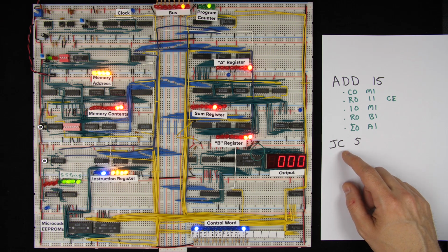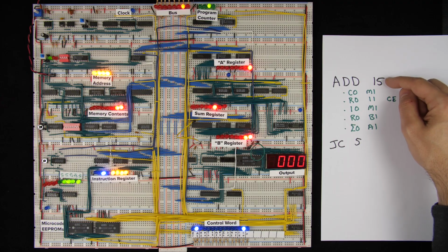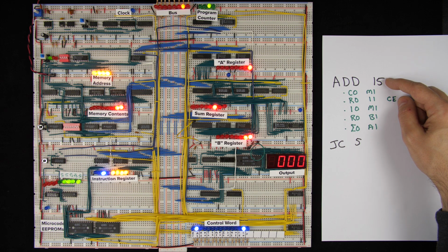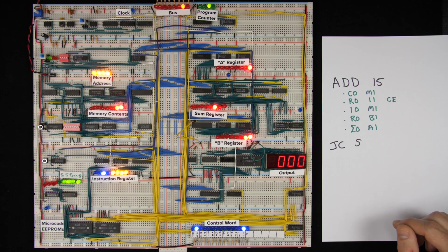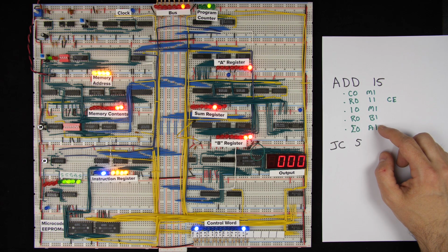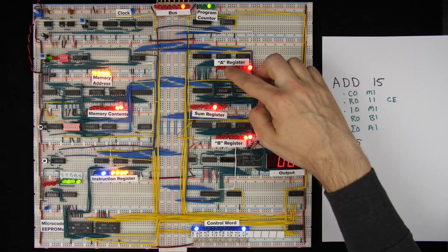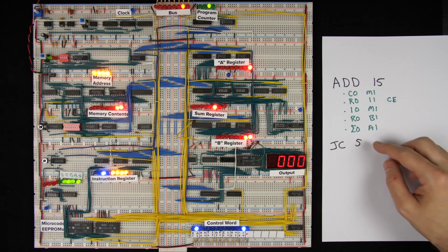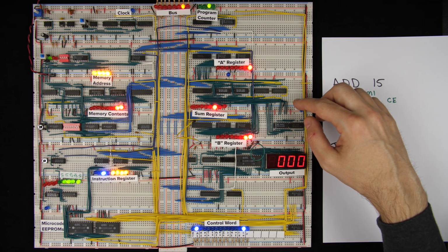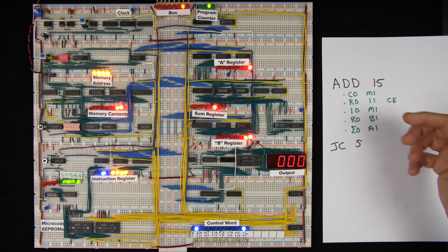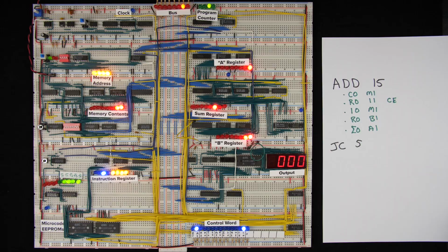How do we keep track of whether this add or subtract instruction that we're doing here resulted in a carry or not, if at the end of the instruction the carry bit isn't set anymore? Well, what we've got to do is that on the last micro instruction here, where we take the result and put it into the A register, we've also got to take the result of the carry bit and the 0 bit for that matter and put them somewhere. So how can we store these 2 bits somewhere where we know they won't change unless we explicitly update them at a particular time during the execution?